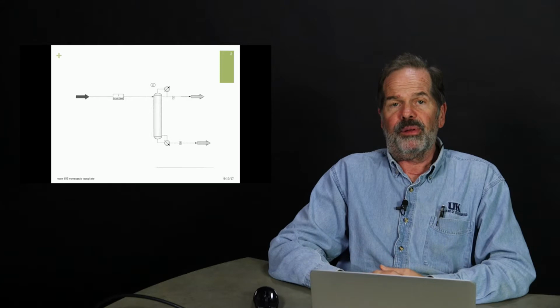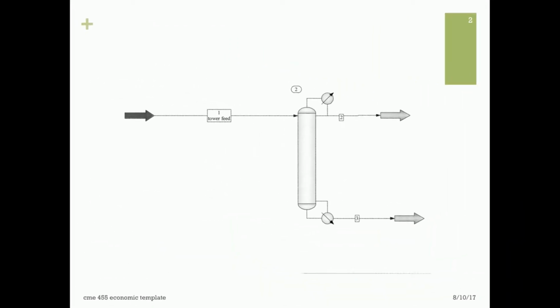So here's an example. If you remember, we were talking in the distillation piece on a separation which included a tower. So here's the feed coming to the tower. We don't know the number of stages. This can be a variable. The reflux ratio is going to change how much condenser cooling water we use, how much reboiler steam we need down here. And if you remember, we need to be able to plot